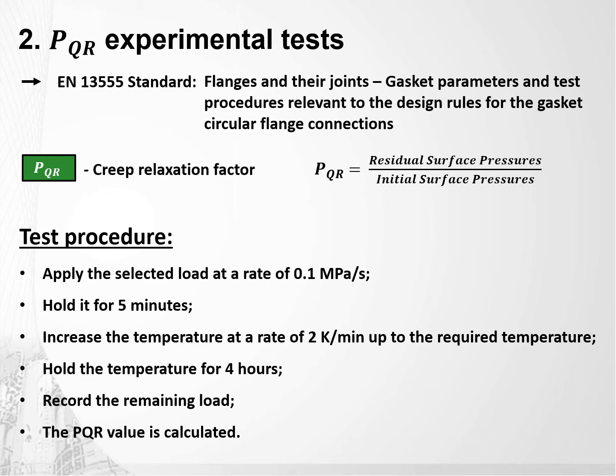It has a test procedure to measure PQR, which is the creep relaxation factor, and it's measured as the residual surface pressure over the initial surface pressure. Therefore, you can consider PQR as the remaining percentage of the stress you have applied to your gasket. As an example, a PQR of 0.3 means that only 30% of the total stress you applied on your gasket at the installation time remained after the test.